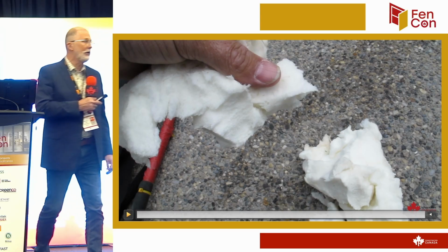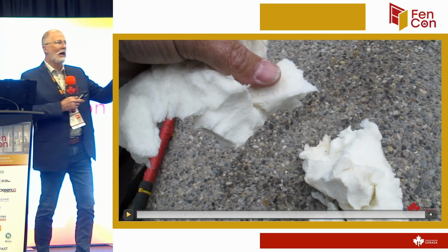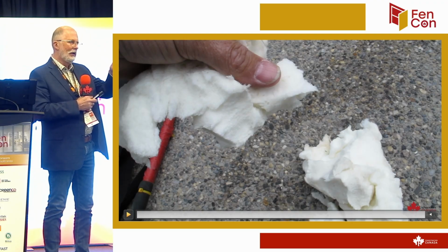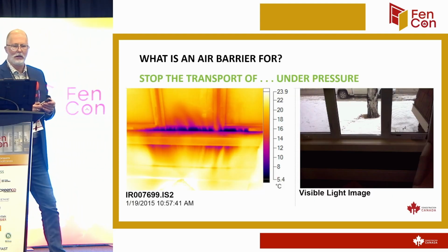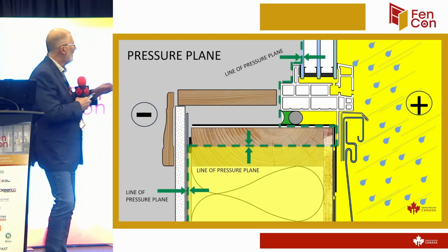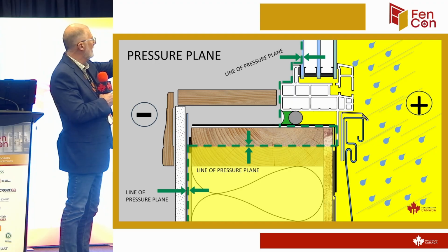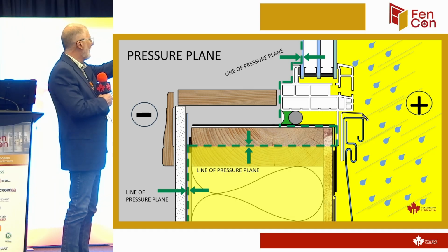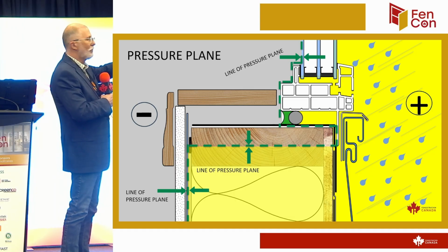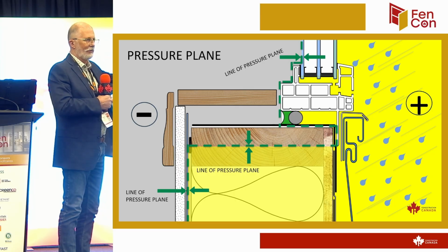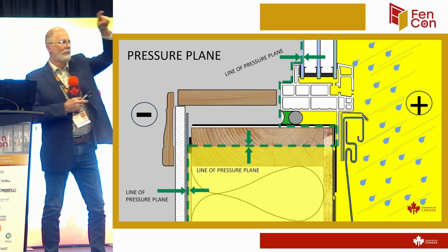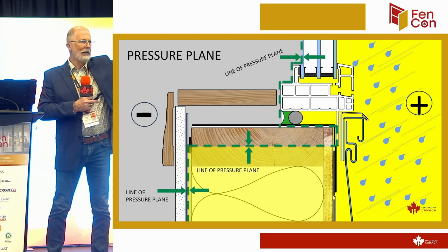Well, yeah, it is possible. It is possible, but how would it get there, I guess, is the question. So if you look at the design in that cross-section, let's back it up for a second here. Let's look at this detail here. So see where I'm showing the closed backer rod in the caulking. If water comes in from the inside of that, that's absolutely possible, but how would it get there, I guess, is my question. Because you've sealed it four sides.